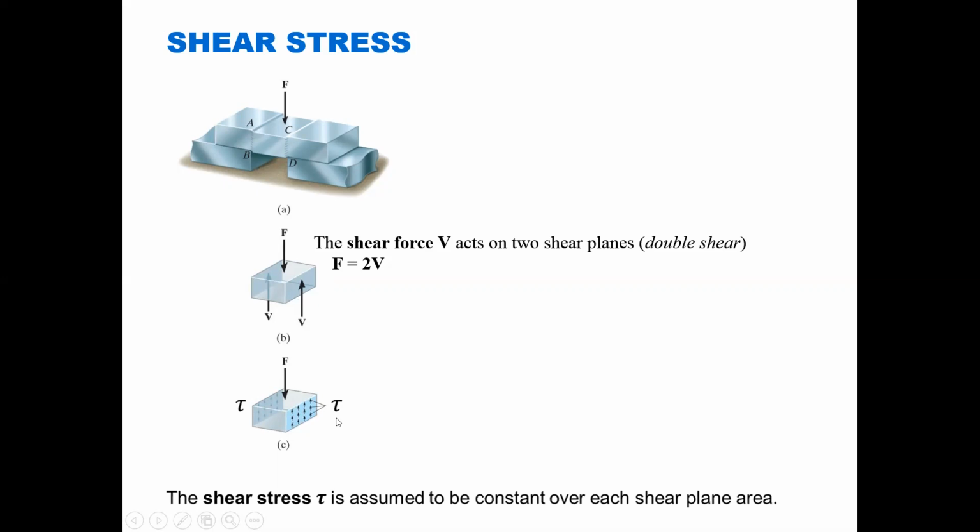Okay, now in the textbook and in almost any reference you find, whenever shear stress is discussed, there will be this Greek letter tau that's used, to distinguish the sigma for normal stress from the tau value of shear stress. Okay, so it's important that you recognize these are not just arbitrary Greek letters that are being thrown out, and you need to use sigma when you're using normal stress and tau when you're talking about shear stress.